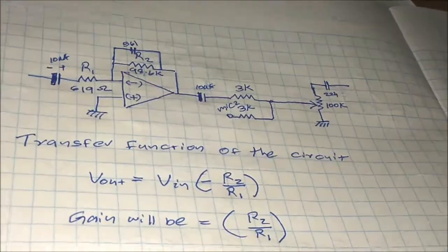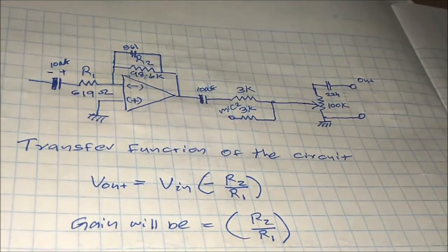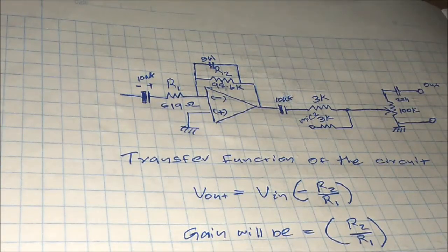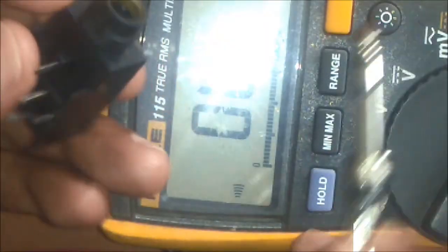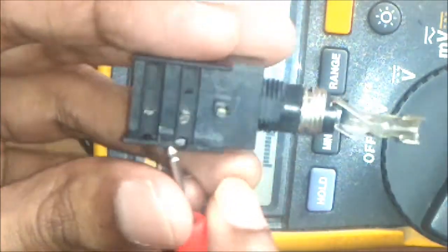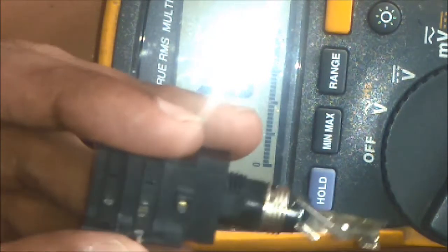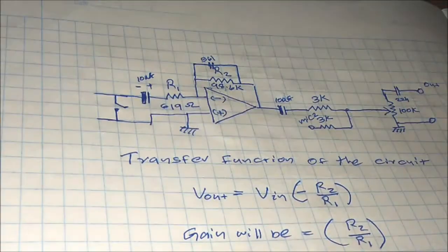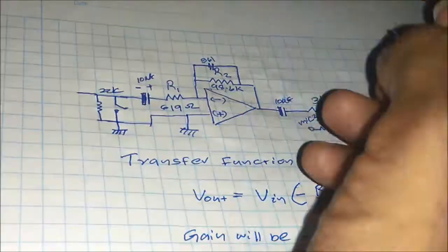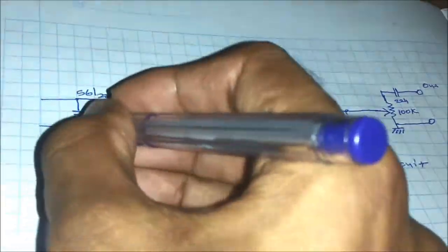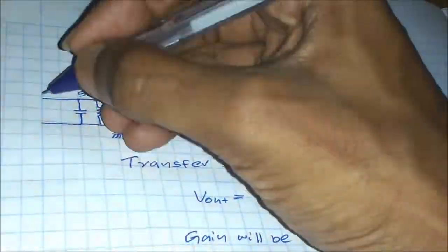If a microphone is not connected, the input terminal is open, which can pick up external noises. We can use an inbuilt switch in the microphone connector to prevent this issue. I'll show you with my multimeter. It turns on if a mic is disconnected. It turns off if a mic is connected. We can use that switch to ground the input when the mic is not connected. Also a capacitor and a resistor to prevent making horrible noise if you connect or disconnect the microphone while operating.